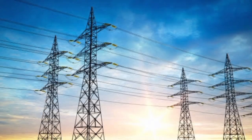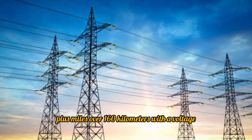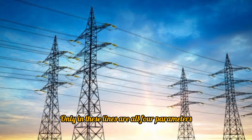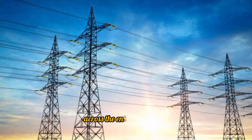Long lines. A long power line covers a distance of 100 plus miles, over 160 kilometers, with a voltage capacity of 132 kV or above. Only in these lines are all four parameters used for determining performance: resistance, inductance, capacitance, and leakage conductance equally distributed across the entire power line.